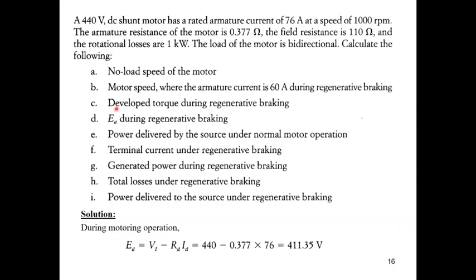The third part: find the developed torque during regenerative braking. Simply, we have the current and we have the value of K phi, so we can multiply K phi by I to calculate the developed torque.